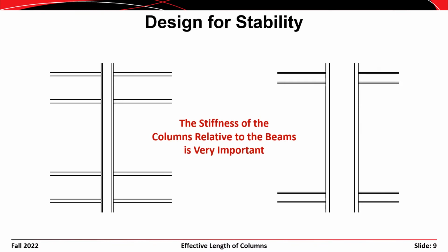The takeaway from this slide is that the relative stiffness of the column being considered and the beams framing into its ends is an important consideration in the determination of the effective length factor for a column.